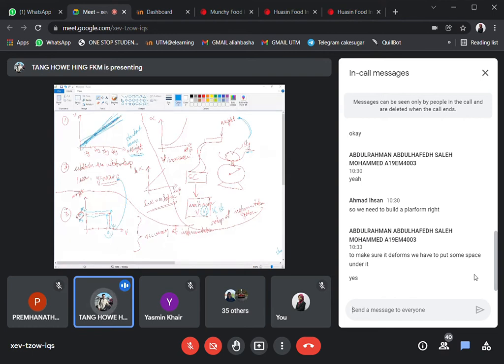Okay, so this is just a statistical analysis part. So how to use it, this one I leave it to you. All right, and then later on in step number 3, this standard or known weight, actually you can reuse it again, but this round you do it in a different way. You load it to the load cell and then you measure the voltage and then you get the readings.